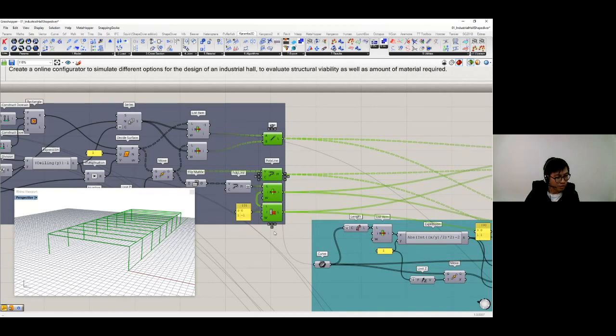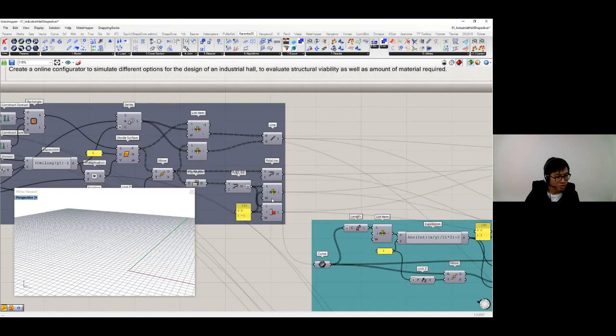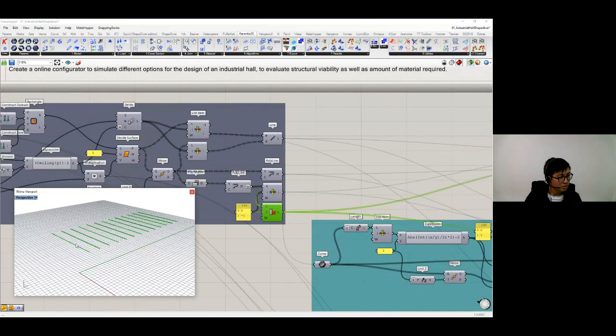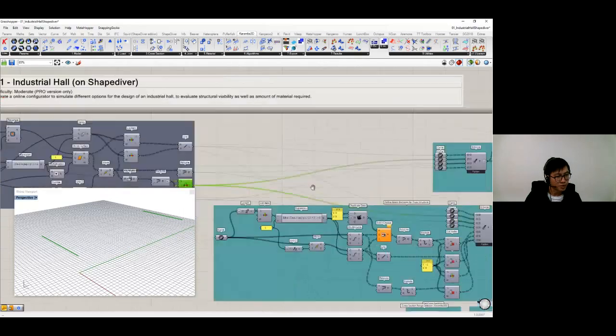And what I've done is to apply them rather than as a mesh load, which takes a bit more computational time, as line loads. And as I wanted to define them as line loads, which have a regular, consistent line load in the middle base rather than on the edge base, that's why I've split these into different lists here.